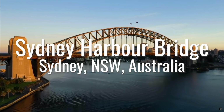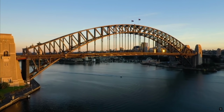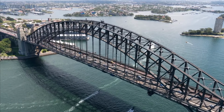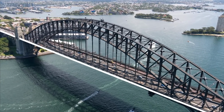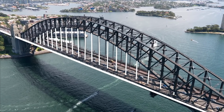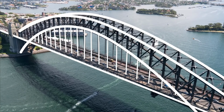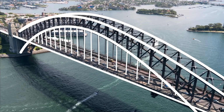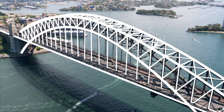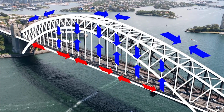So the City Harbor Bridge employs two trusses in the shape of an arc, and it also is the type of arc that we refer to as a through arc bridge, such that the deck is not above the arc, but is in line with or beneath the apex of the arc. There are also vertical struts that connect from the truss arcs to support the deck through tension. This aligns with the use of the elements within the truss as well, which are also designed and put in place to only experience purely axial forces, whether in compression or in tension.